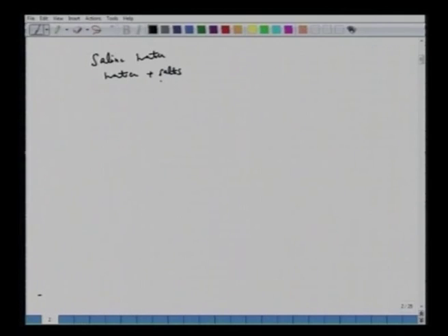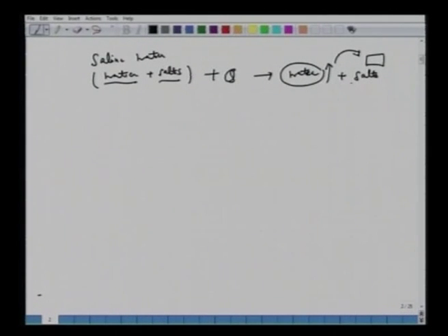The salt is relatively small, water is a very large quantity, and if you recall some unit operations where you supply heat, the water will evaporate, you take this water, condense it, and you have some salts left, sodium chloride, etc. Now this unit operation is evaporation, it's not drying. In drying we will see that some steps are very close to evaporation.